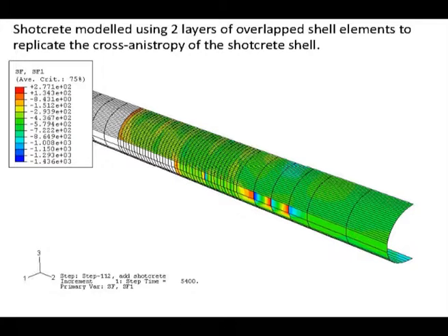You see, the guy who designed a lot of this geotechnical structure designed it in 2D. When you analyze a diaphragm wall panel in 2D, it's just 2 wall panels like that, and there's no 3D action here. In fact, the joint between diaphragm wall panels is undefined, to say the least.